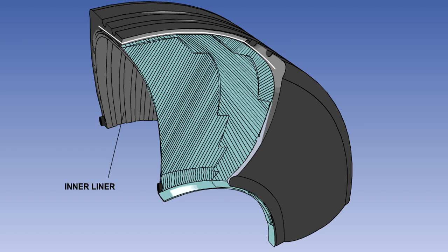If the tyre is designed to be used without an inner tube, a rubber lining is applied to its inner surface and the underside of the beads. This lining, which retains the gas pressure, forms a gas-tight seal on the wheel rim. The gas seal depends on a wedge fit between the underside of the tyre bead and the taper of the wheel rim.